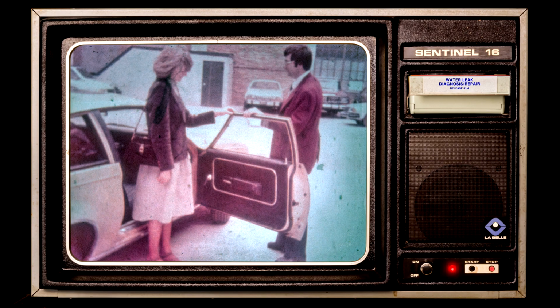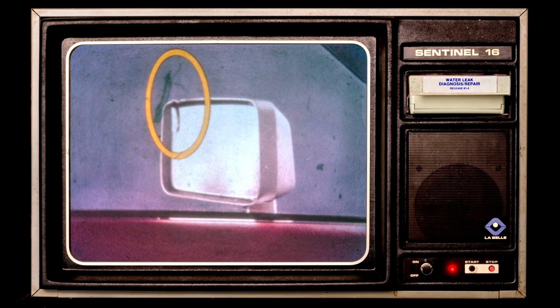When discussing a leak problem with the customer, the service advisor can avoid wasted diagnosis time by asking the right questions. There's one particular question that should always be asked. Has the customer simply noticed water accumulating in a particular area? Or has he actually seen water dripping? Obviously, if he can show you where he spotted water dripping, you'll be that much closer to locating the leak.